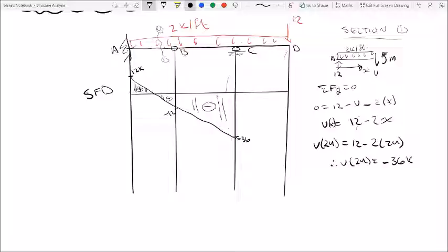So if we're at minus 36 right now, going from left to right, then we need to bump it up 72, and we'll get to a positive 36. And then we know that we're still at a UDL, so we can just connect the dots. There are no important points in between, so it'll just be a straight line all the way back down to 0.